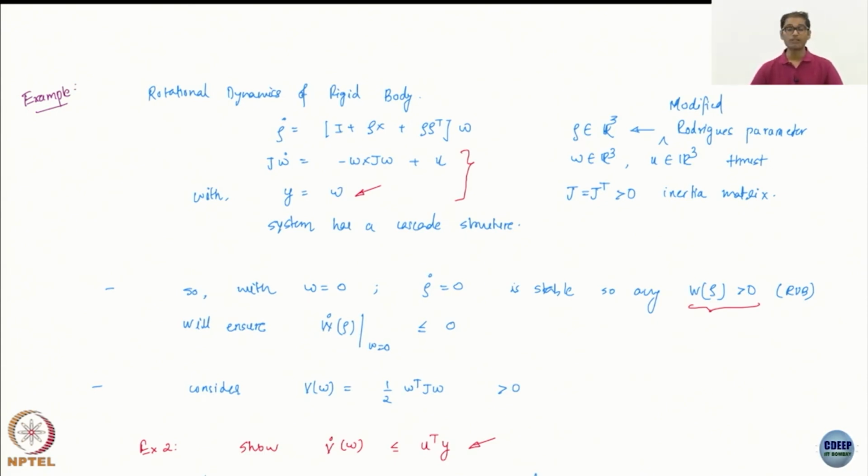Okay, because these are two very, very far reaching tools. Yeah, in fact, backstepping and passivity are also very closely related, because you can use the backstepping ideas, if you remember, the idea of backstepping was to just get CLFs, right? If you keep adding systems, you keep getting newer CLFs. So you can use those CLFs as storage functions for the passivity. So it also helps you construct storage functions. You might be able to use that storage function to gauge passivity and then do a design. So these things can also be combined in a very nice way.